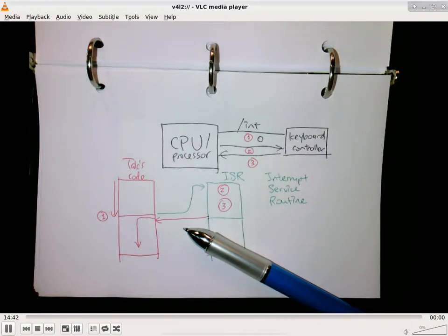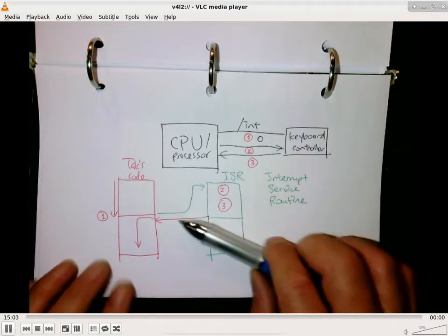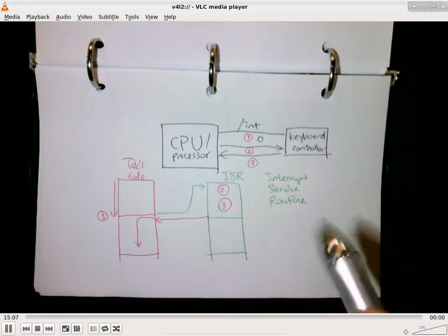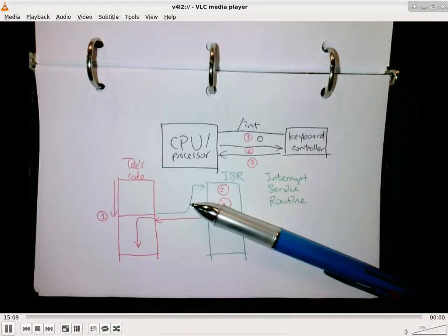It goes on the stack, exactly. It is just like a call, except it is not done by opcodes. It is done by the hardware. Okay? It stores it, right. Exactly. Because I have no control over where the green line happens. The green line can happen over here in my code. It can happen here in my code. I have no idea. This is an asynchronous event.